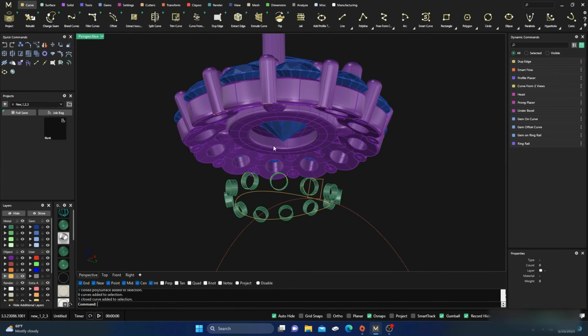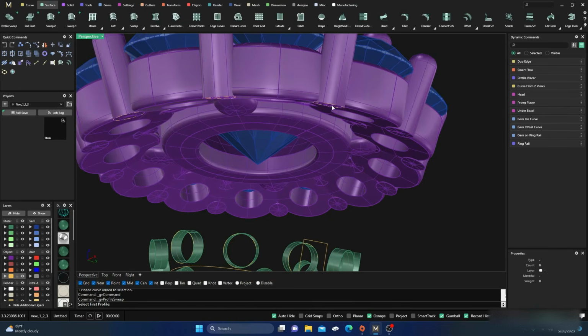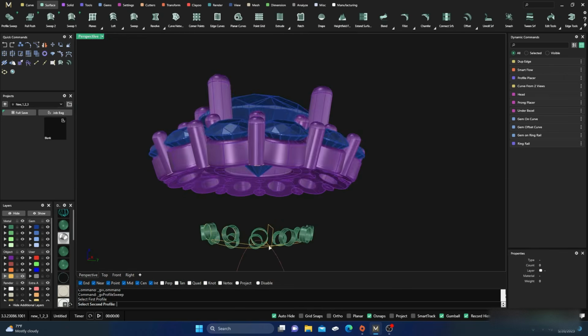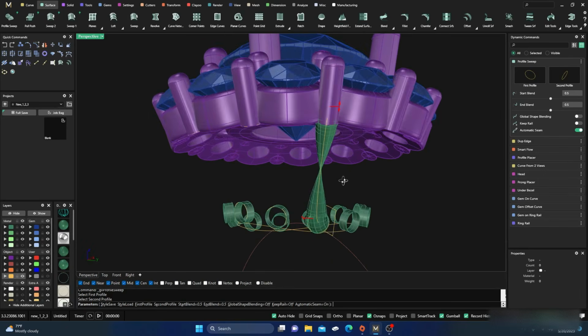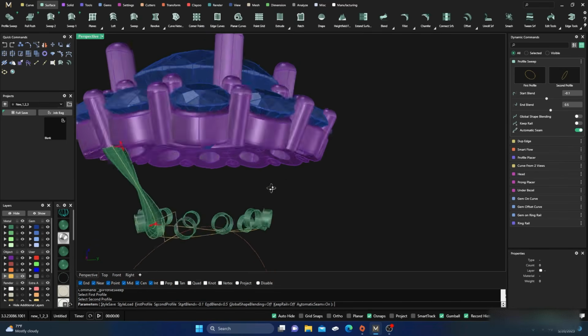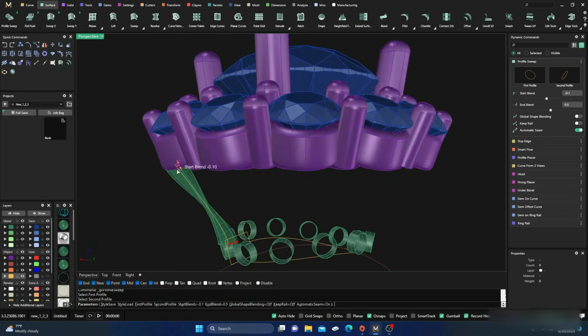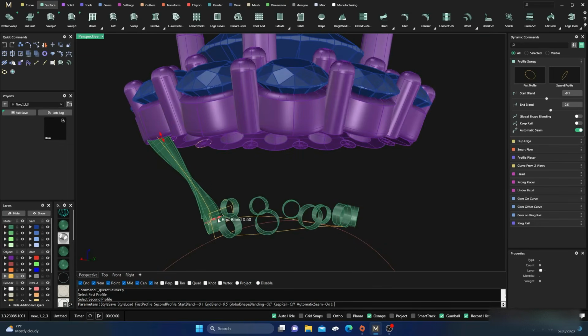So let's just start with this one here. We'll go to our surface here. We'll do a profile sweep from this circle here to our little circle down here. And of course you get that there. No worries, don't be worrying about that. First of all, you want to drag this one down. I usually take it down to a -0.1, and it seems like it keeps it as close to the curve, or usually pretty close once it's all done, a little bit easier.